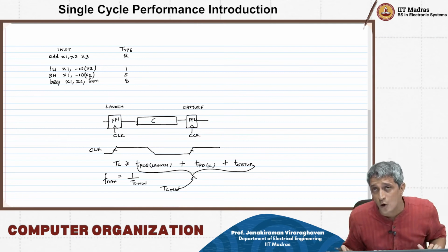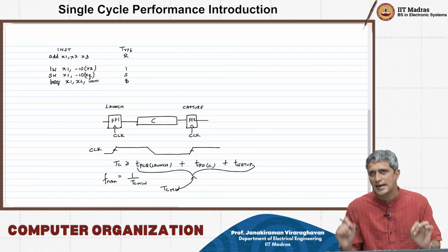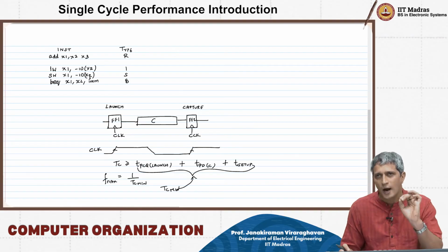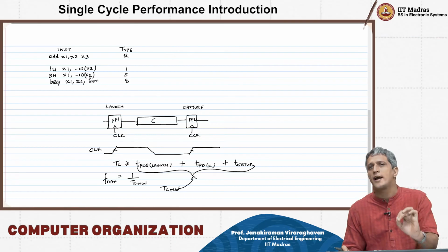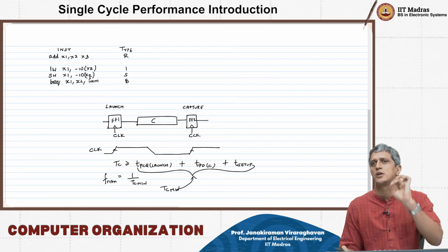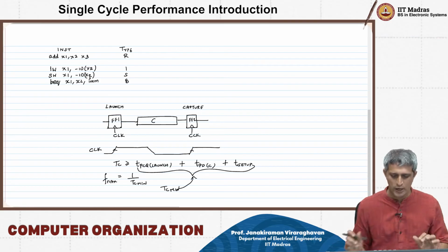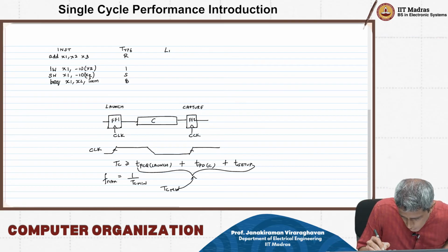Therefore, in order to do this static timing analysis, the first thing you need to do for every kind of instruction is to identify which is your launch flop and which is your capture flop. So let us go ahead and do that.